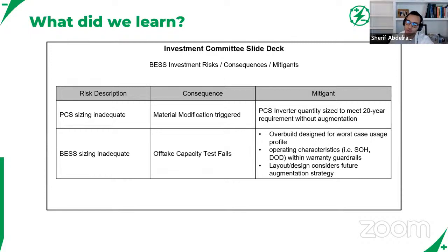We did the deep discharges and the shallow discharges, and both of them were one cycle a day. And I think what we found with the specific LFP battery model we utilized was that the shallow discharges were less impactful on degradation than the deep discharges. So in this case, if you're using that same battery model, you're probably looking at a more economical first case you have here, going from 30% to 70% state of charge back and forth.